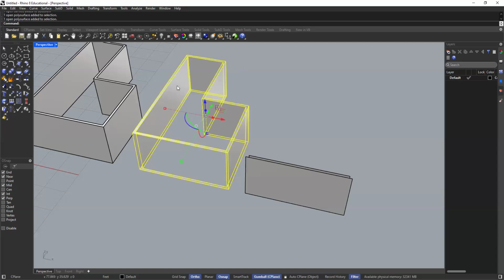And later on, we're going to have to start doing things to this polysurface, and it's just not going to work for you. Because the next step of cutting out doors and windows and things like that requires these objects to be polysurfaces. And if there's anything wrong with it, the command's not going to work for you.